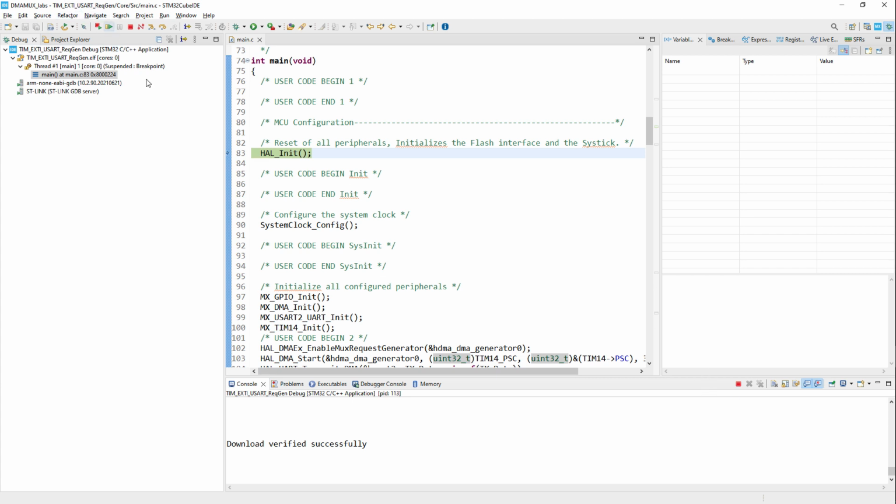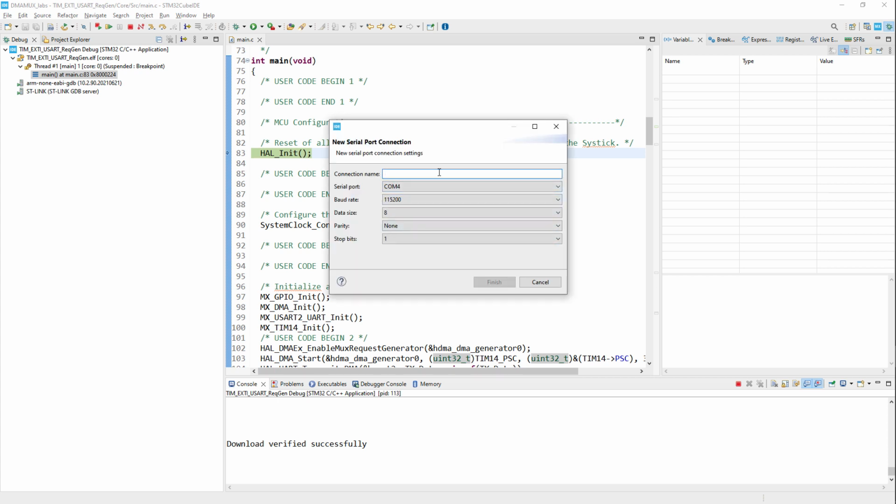So before starting the project, let's go below, and within this Open Console button, I click on this down arrow, select Common Shell Console, serial port as a connection type, connection name, I will select something different, let's call it TT, serial port, usually the highest possible numbers as virtual COM port are landing over there.